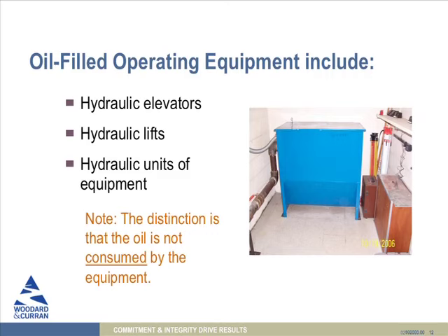Yeah, easily. And so some campuses may not even have tanks, or may have one small tank, but if you've got a couple big transformers, that's going to put you above the threshold anyway. So you have to make sure you look at all of these things in determining whether you're subject to the oil SPCC program. All of these things you have to look at in figuring out if you're at that 1,320 gallons. And again, only 55 gallons or more. So say this hydraulic elevator reservoir held 40 gallons, it doesn't count in your calculation, and it's not subject to the rules. There's a 55-gallon threshold.